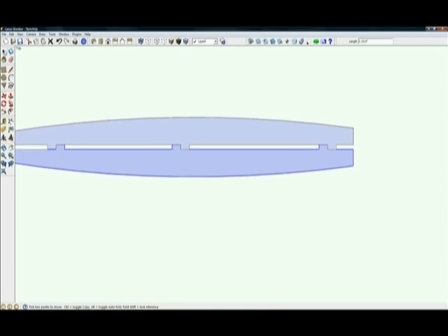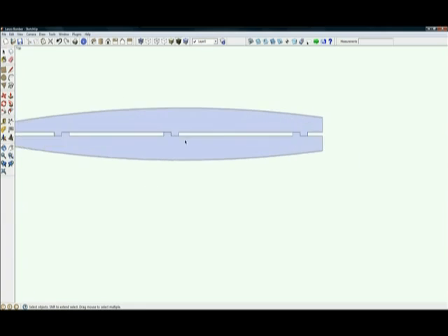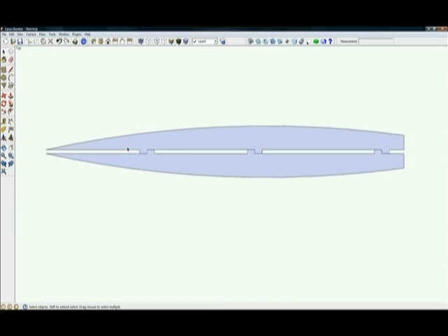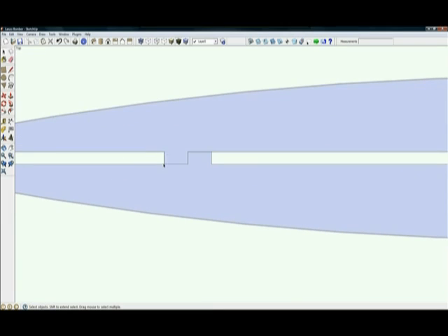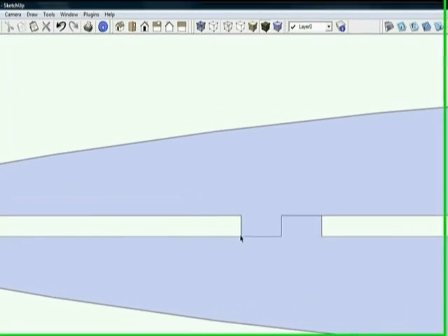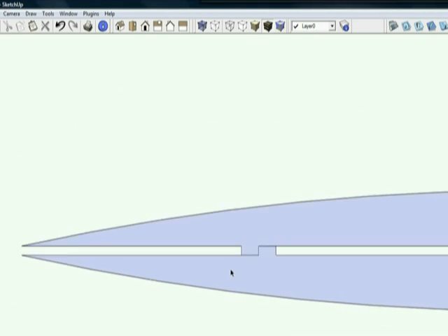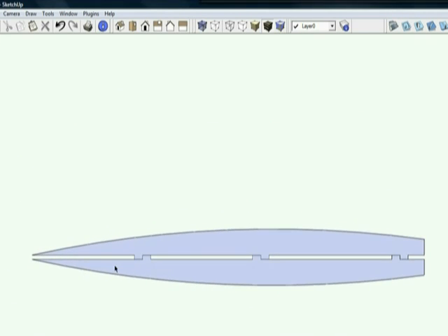But what I basically did to pull this off is I just worked up, I figured, okay, my material is 6 millimeters thick, so the spacing in here, from here to here, that's 6 millimeters. And then I made the side braces like I wanted. And then I determined, well, I think I would like to have 3 of these, one in the middle, one near the nose, but not all the way to the nose because we want strength up there. And then one back here.